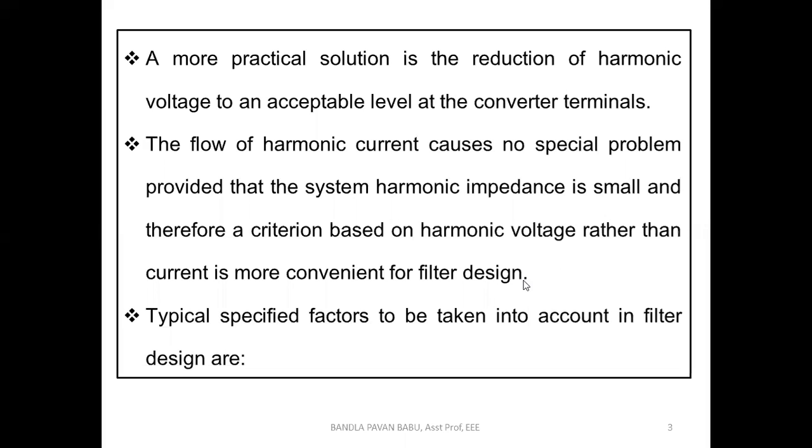Adding impedance may lead to an increase in losses or in line reactance, so obviously some issues will be there. If we attach anything to the line, there will be a change in the system parameters. But by placing these filters it will not be a big issue, because all the impedances we choose for harmonic reduction are very small.